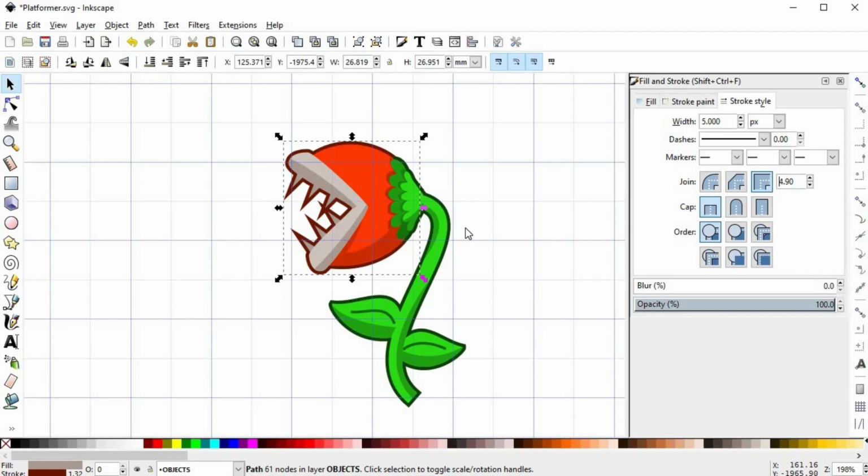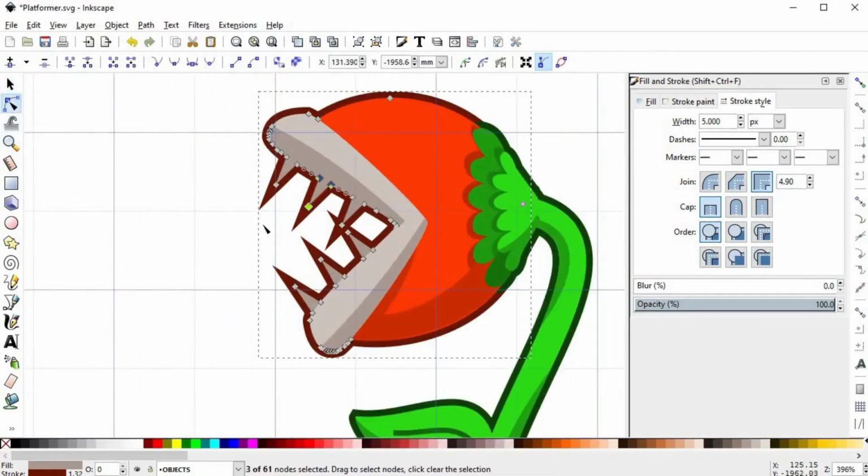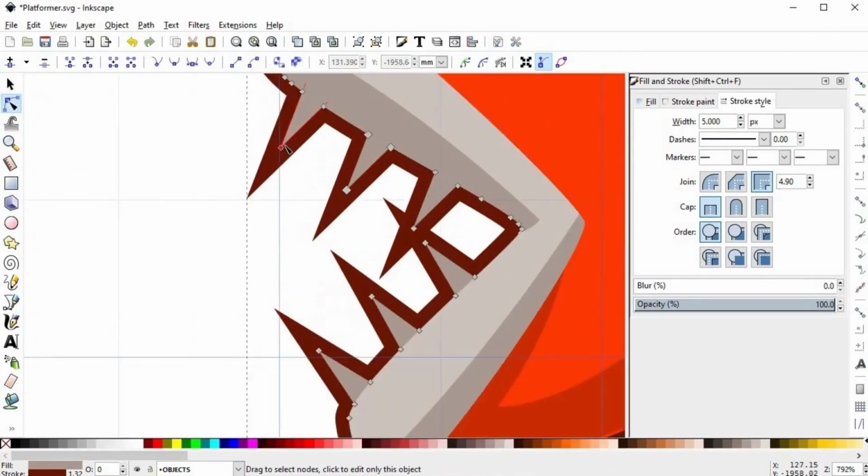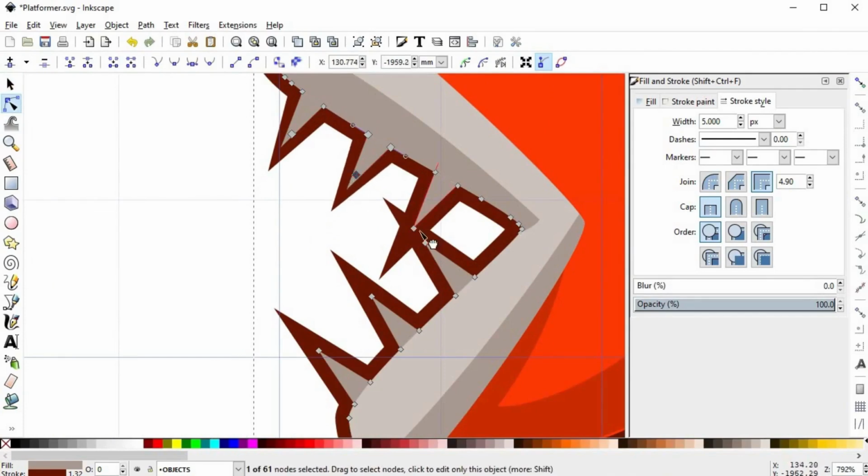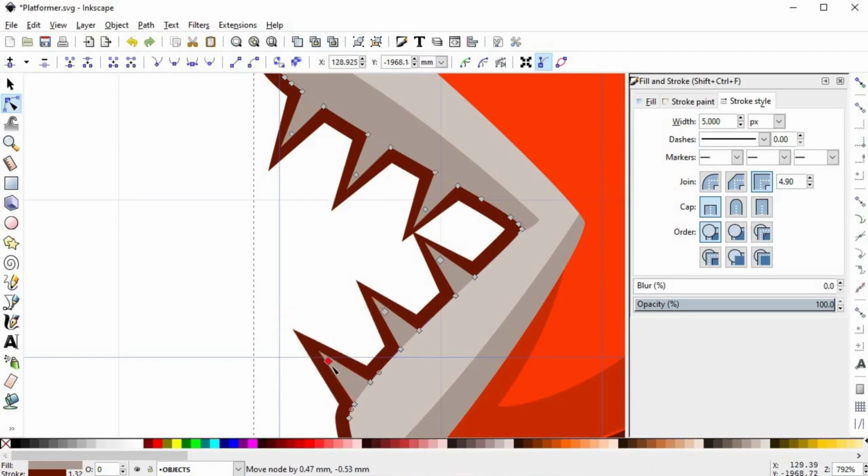Well, the only solution to this problem, while keeping the stroke nice and thick, is to go in there and modify the shape of the stroke manually with the node tool. Modify the nodes, pulling them back a bit, while trying to keep the biggest quantity of stroke outline in each tooth. If you see that you can't show enough outline because the position of the teeth makes it really hard, you could pick a tooth and move it slightly to the side and adjust the outline accordingly.